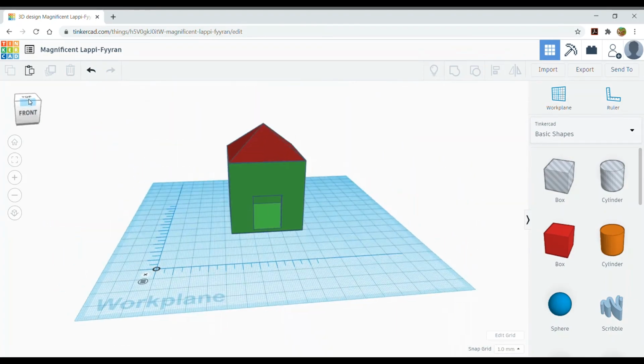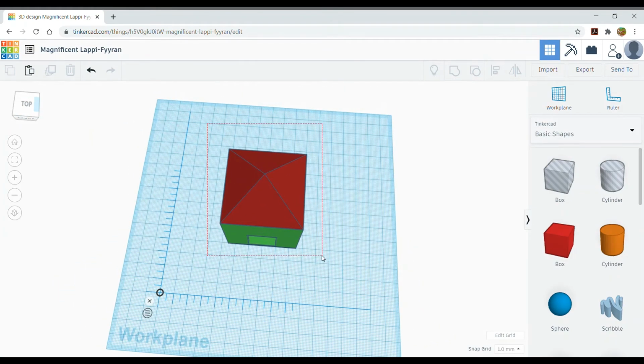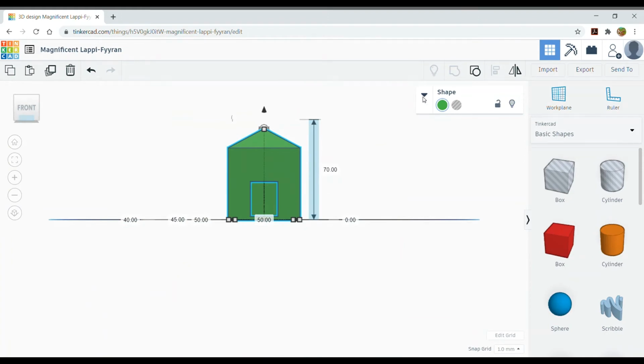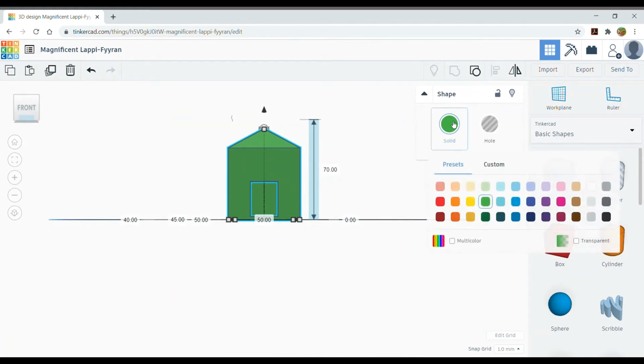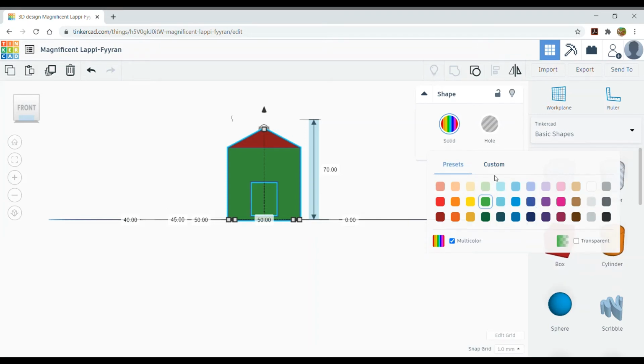And let's say you wanted to group these two together, you can do that, but then what happens is the color changes. It makes all of them have the same color. So how do you avoid this? Well, one way to do that is to click the color and instead click multicolor. Oh, by the way, there's also custom colors, so you don't have to specifically stick to these colors, so you can even take your own custom color.